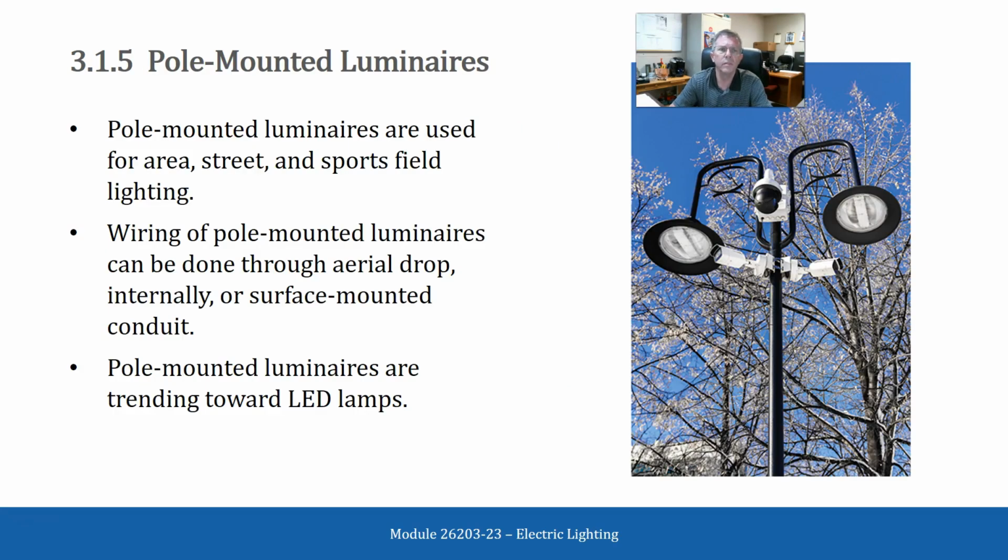Pole-mounted luminaires. Pole-mounted luminaires are used for area, street, and sports field lighting. Wiring of pole-mounted luminaires can be done through aerial drop, internally, or surface-mounted conduit. Pole-mounted luminaires are trending towards LED lamps.